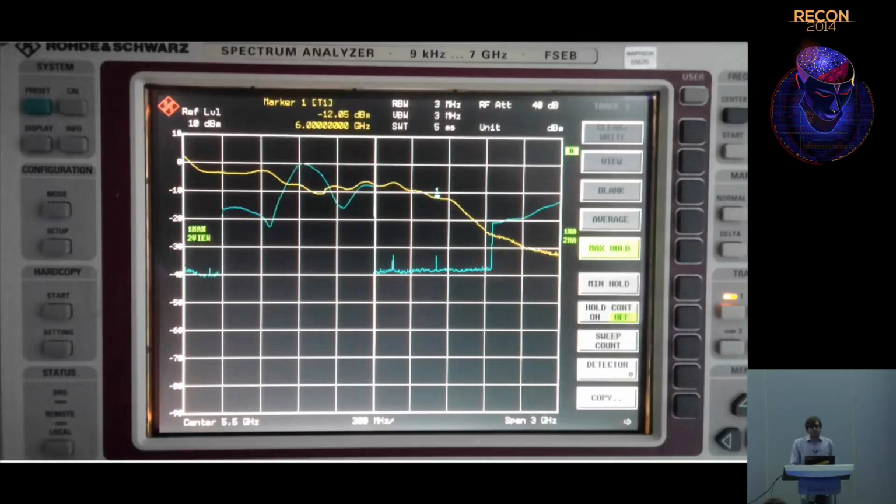And in some cases, especially on the very high end, we can actually get better maximum output power from the transmitter, like way up at 7 gigahertz, just by exploiting the harmonics of the intermediate frequency instead of actually trying to mix it up in that front-end mixer.